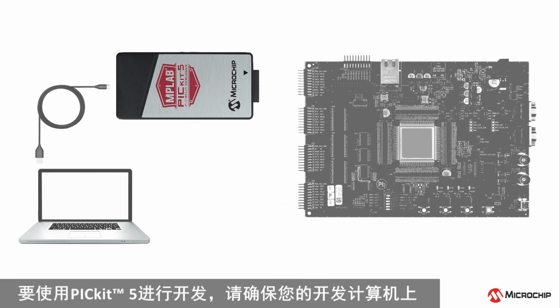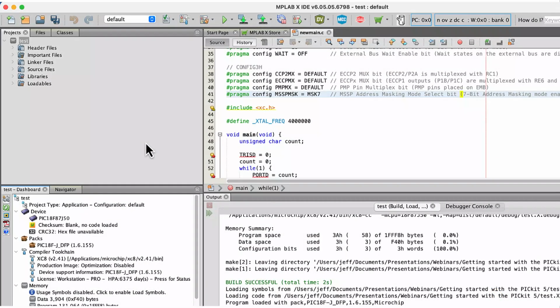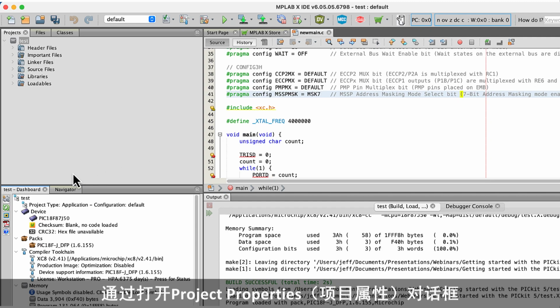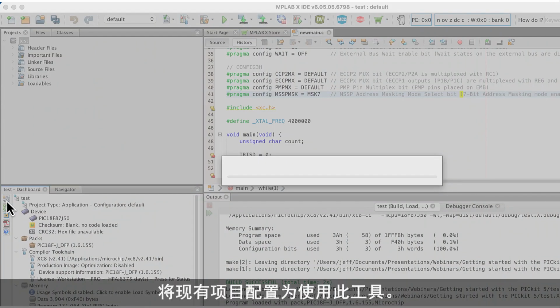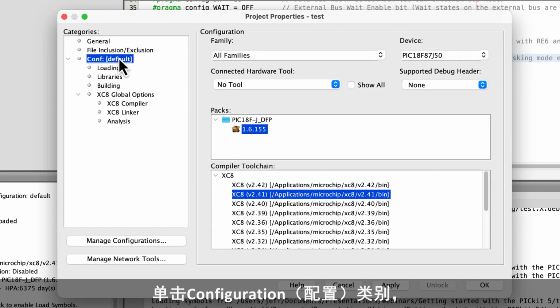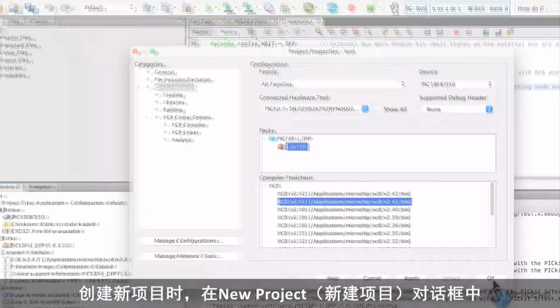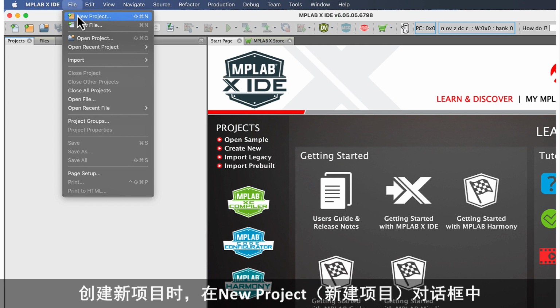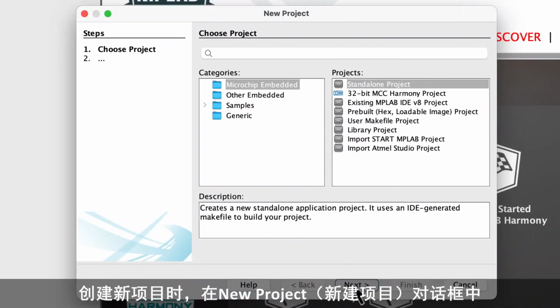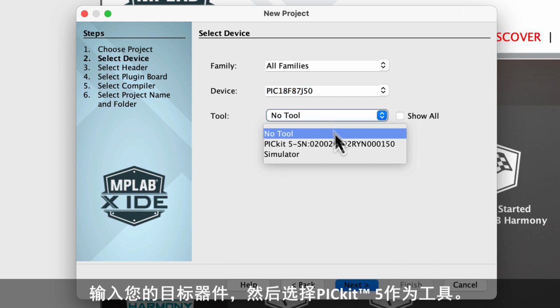To develop with the PICkit 5, ensure the latest version of the MPLAB X IDE is installed on your development computer. Configure existing projects to use this tool by opening the Project Properties dialog. Click the Configuration category and select PICkit 5 from the list of hardware tools. When creating new projects, proceed through the New Project dialog, entering your target device, and then select PICkit 5 as the tool.